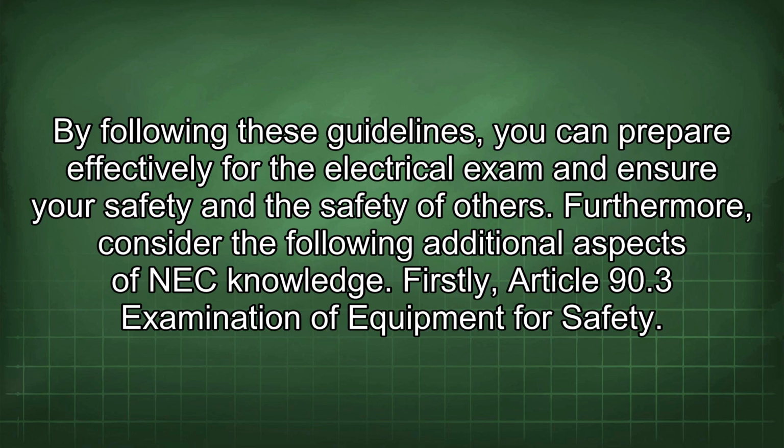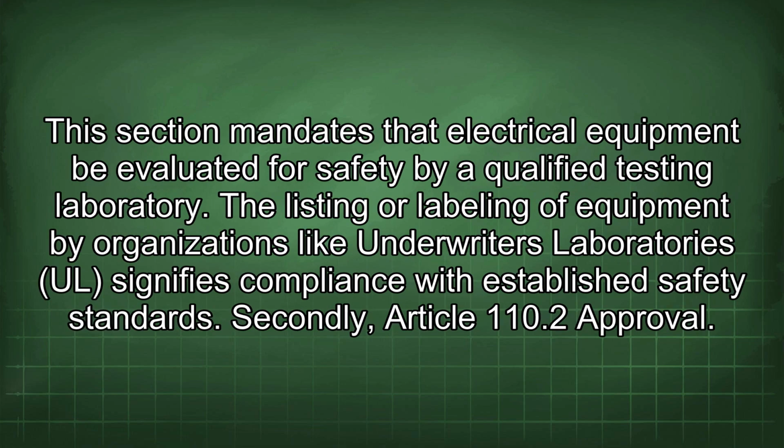Firstly, Article 90.3 Examination of Equipment for Safety. This section mandates that electrical equipment be evaluated for safety by a qualified testing laboratory. The listing or labeling of equipment by organizations like Underwriters Laboratories (UL) signifies compliance with established safety standards.